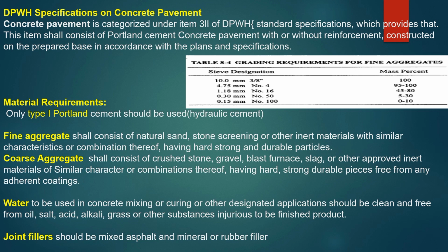So, the other one is the water. Water to be used in concrete mixing, curing, or other designated application should be clean and free from oil, salt, acid, alkali, grass, or other substances injurious to the finished product.